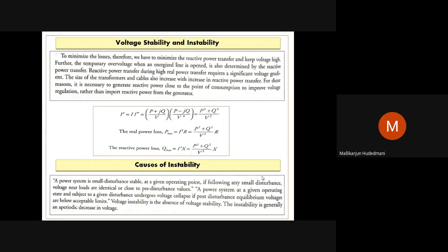So why are we trying to do this? Because the loss due to the active power component is I square R, nothing but your resistive part, and the loss due to the reactive power component, the inductiveness, is measured with I square X. To compute it, we require the current in terms of the system's active power, reactive power and working voltage levels. In that notation, the representation is current square equal to P square plus Q square over V square. This becomes very necessary for us to understand.